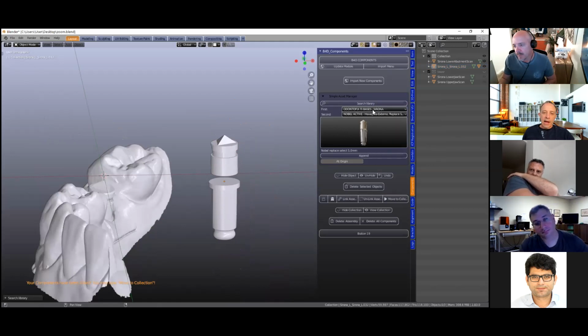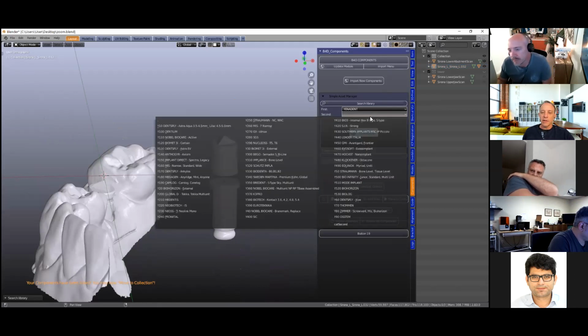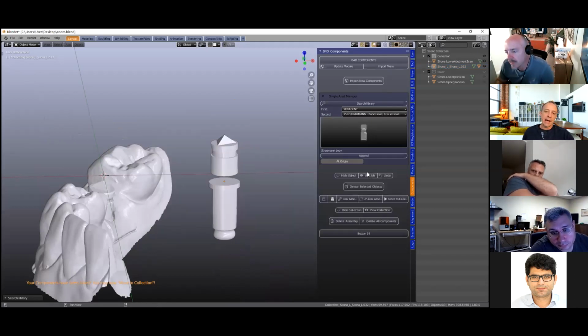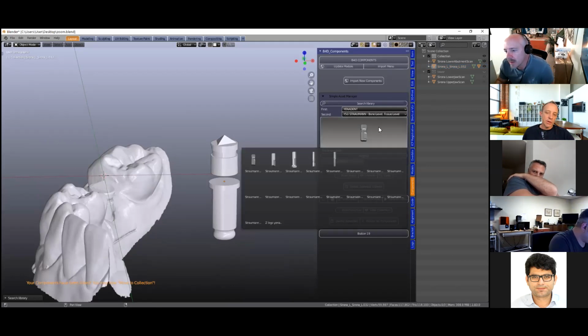It's easier if we have them all stacked into an assembly, and then by going into transparent mode, you can pick out only the components you want, and the ones you don't want you can delete or put into a different layer. So this is why it's important to go into transparent mode.